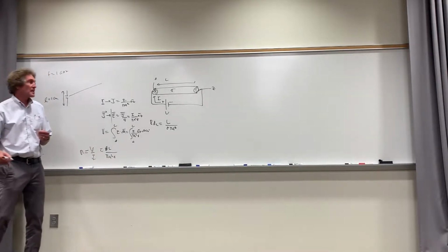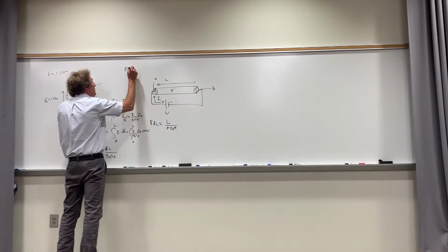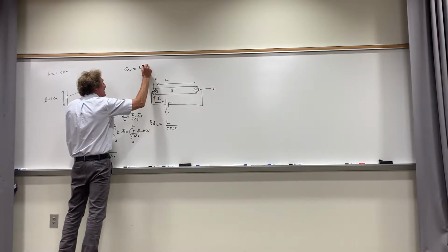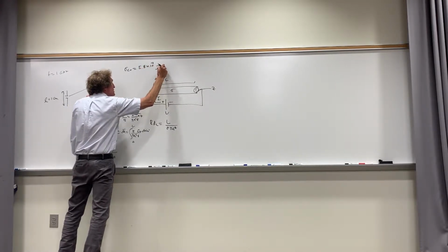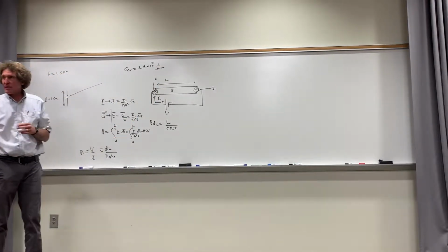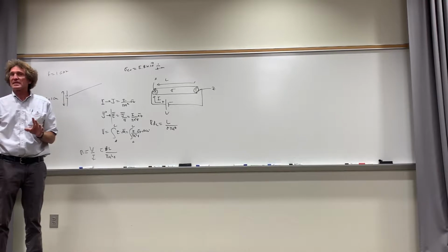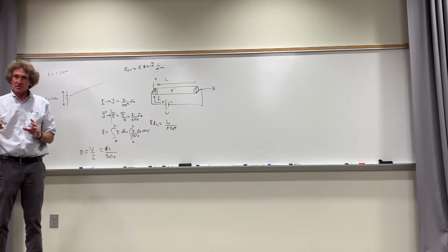Now, if there's a skin effect, and so for copper here, sigma of copper is equal to about 5.8 times 10 to the 7th, in units of 1 over ohm meters. You can look that up in the back. Does it have 5.7 or 5.8? About that. Now, there are variations with things that are added. They sometimes have an alloy, but that's close.